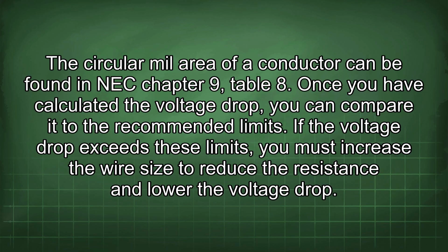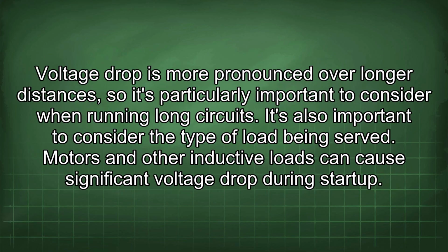Once you have calculated the voltage drop, you can compare it to the recommended limits. If the voltage drop exceeds these limits, you must increase the wire size to reduce the resistance and lower the voltage drop. Voltage drop is more pronounced over longer distances, so it's particularly important to consider when running long circuits.